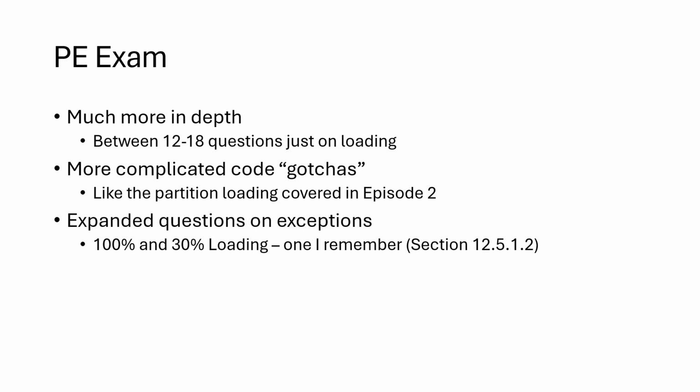If you have certain effects of irregularities or certain things like that, you actually apply 100% of your seismic force in one direction, and then you combine that with 30% of the force for the perpendicular direction of the axis you are designing for.